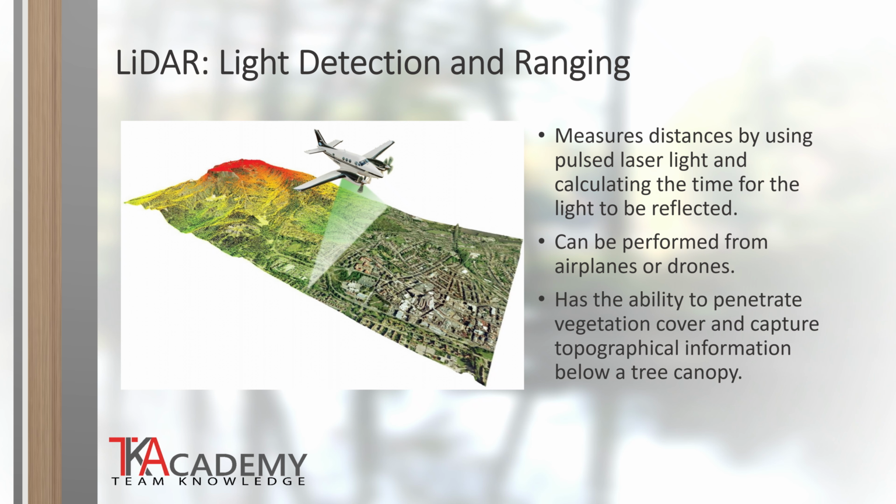LiDAR can penetrate vegetation cover, so it is able to map and capture topographical information below a dense tree canopy. The advantage of using this technology is that it is extremely detailed and can provide a very detailed 3D virtual model of a site.